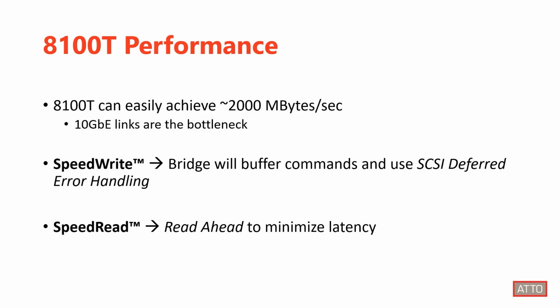Speed write and speed read are ATTO proprietary algorithms which allow us to queue a second command to the tape drive, reducing the latency between commands, which translates to higher performance over the network. With technology like this built into the XstreamCORE 8100T firmware, we can saturate the 10 gigabit Ethernet ports when performing I/O to 4 tape drives simultaneously.